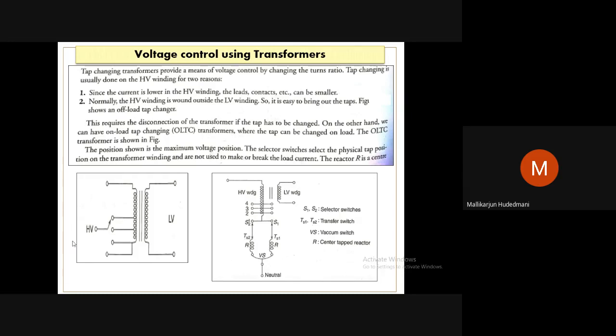The technical reason is that tap changers at higher voltage result in lower switching current. When the tap is switched from 1 to 2, 2 to 3, and back to 2 and 1, the contacts are moving. Definitely there is an arc or spark during the movement of the contacts, and that is with the nominal current.